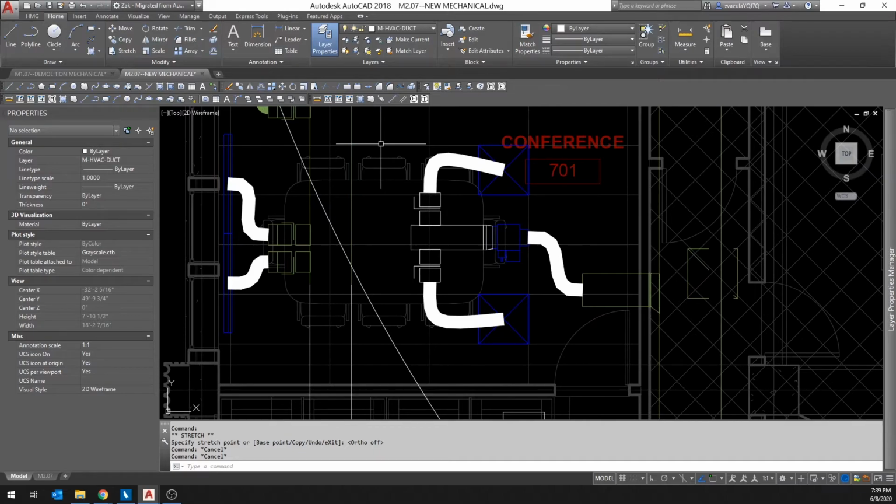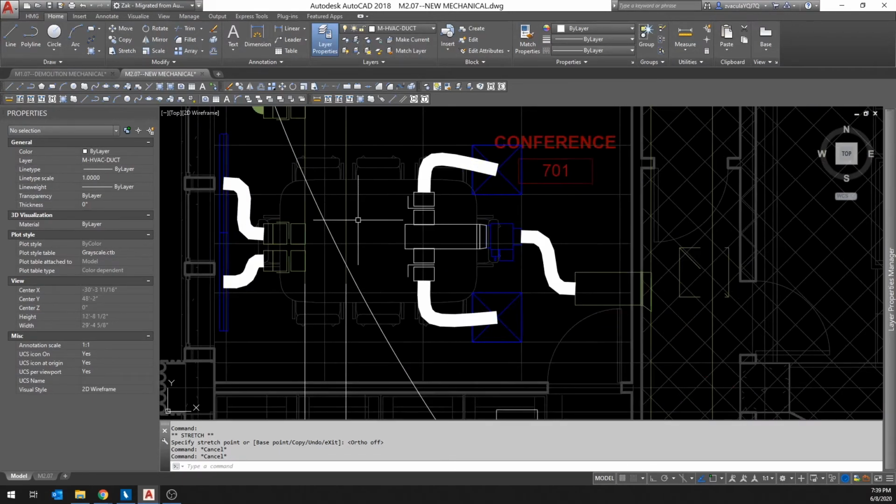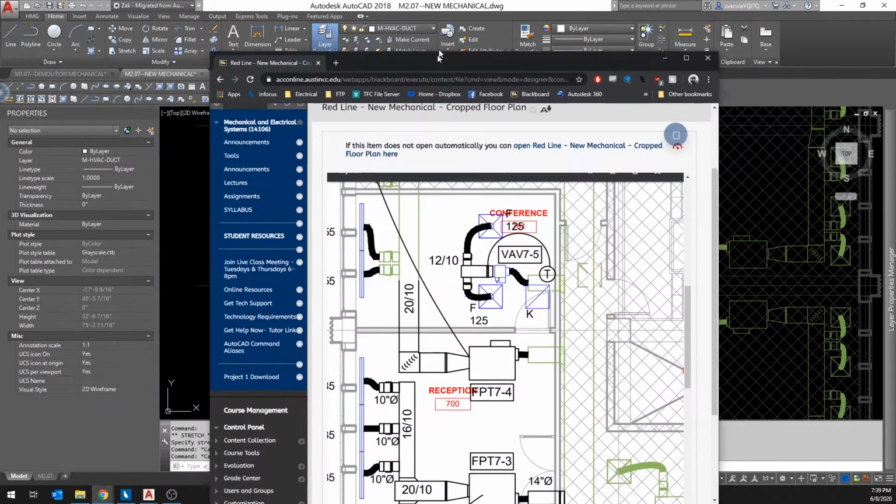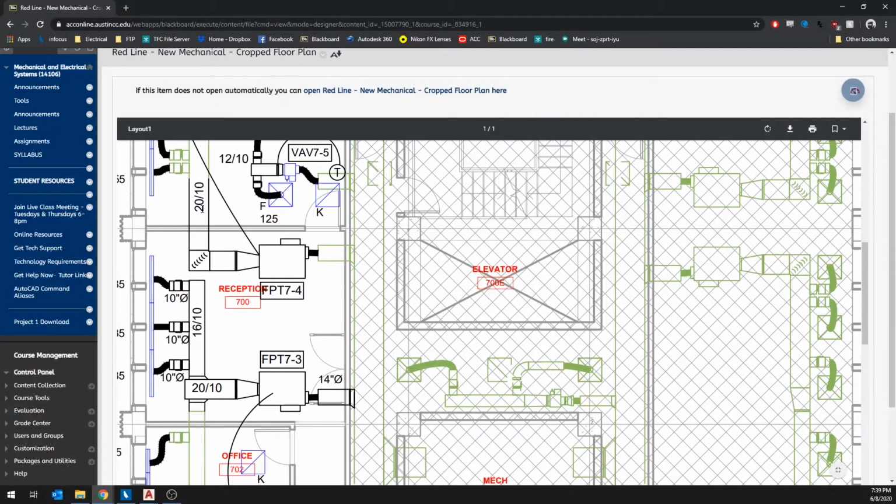up here that without actually being in Revit or anything like that, it's hard to coordinate. Hard to coordinate that exact in AutoCAD. Even in Revit, we don't place a lot of dimensions on our drawings. Maybe mechanical equipment and penetrations through floors and roofs and stuff, we would, but usually for ductwork and things of the sort, we don't. So basically, you'll go through and you will add in all of the